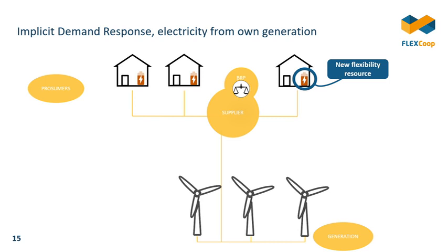So this will be used as a balancing resource and will enable decreasing the costs which are related to balancing, which has been illustrated here with a BRP and the little balance. BRP is the balancing responsible party, and that's the entity which is financially responsible for the balancing of the grid in a given area, which includes the retailer portfolio. Sometimes the retailer and the BRP are integrated, and sometimes it's a third party that is contracted by the retailer. In any case, this flexibility will enable better matching of consumption and generation, and decrease the costs related